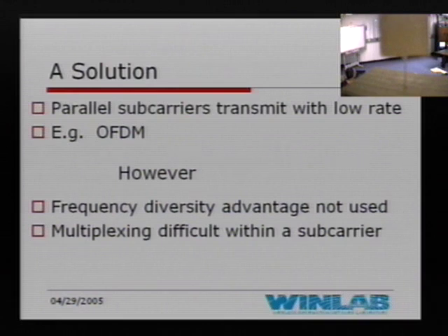Could you ask the question again and you answer it again? Your question was, what can you do? Well, my question was to his remark that in OFDM you cannot put the same bits on 2 carriers. So I will ask why. Yeah, and your answer was? Well, we can, but in most OFDM applications, it's taking one serial data stream and putting different symbols in different subcarriers and doing the IFFT.